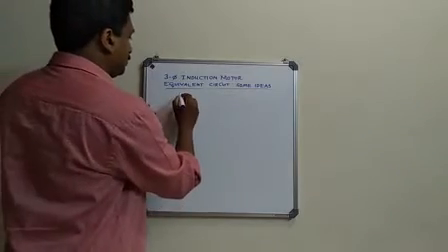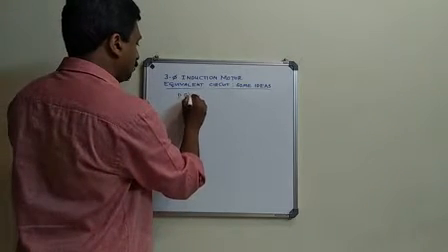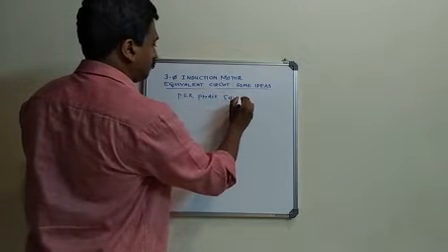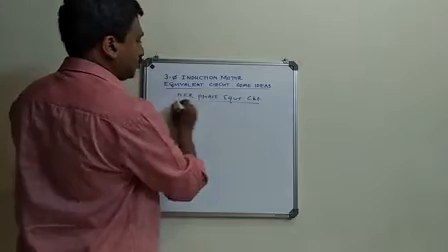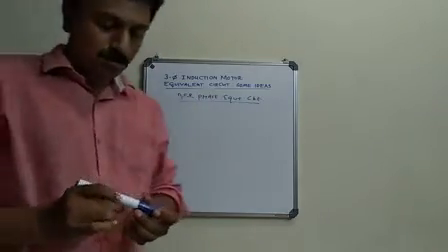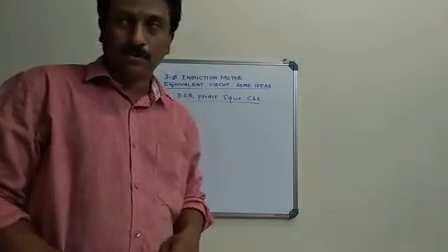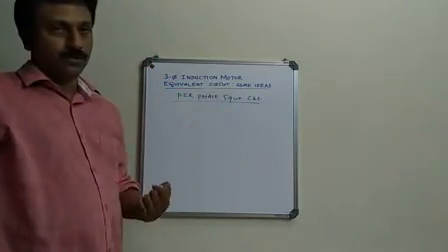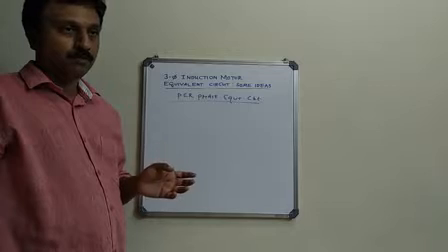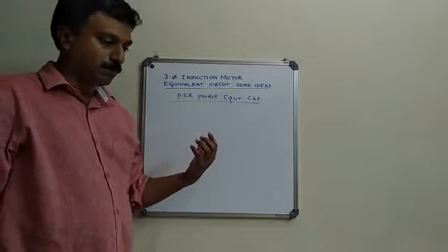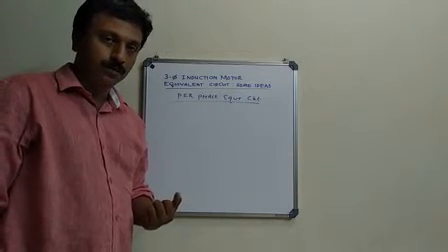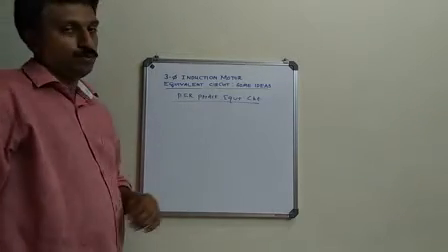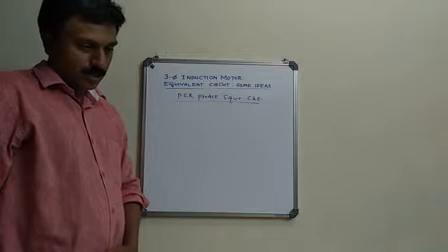Here you will see we are always drawing a per phase equivalent circuit, so all the values are referred with respect to a phase. Then those concepts which were developed in the single phase transformer equivalent circuit can be used here.